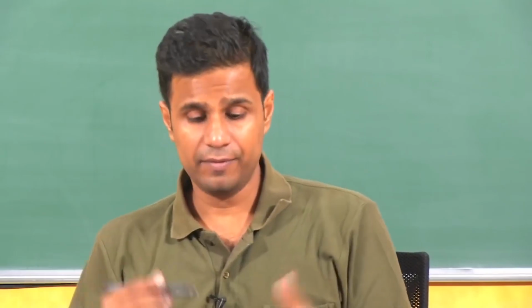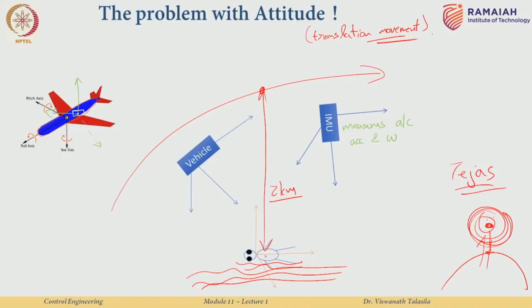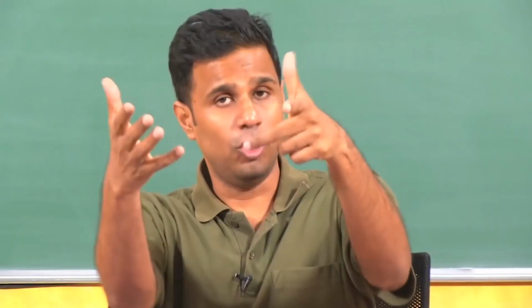So you essentially have now a bigger problem. The pilot in the aircraft, if she or he looks at the data coming from the IMU, so let us say the data coming from the IMU is displayed on the screen of the pilot and it is saying that, look man, let us say your pitch angle, okay, is currently going like this. Now the pilot is not really sure if this is correct or not, because this pitch angle is measured by the sensor and it is not the same as the actual pitch angle of the aircraft because it is in a slightly different position.